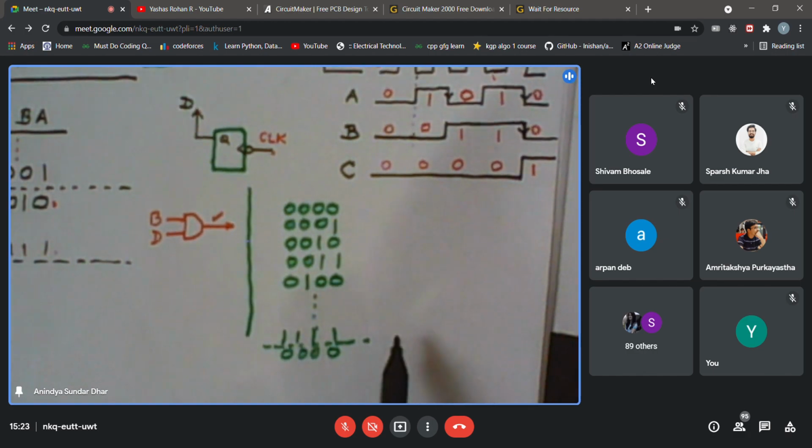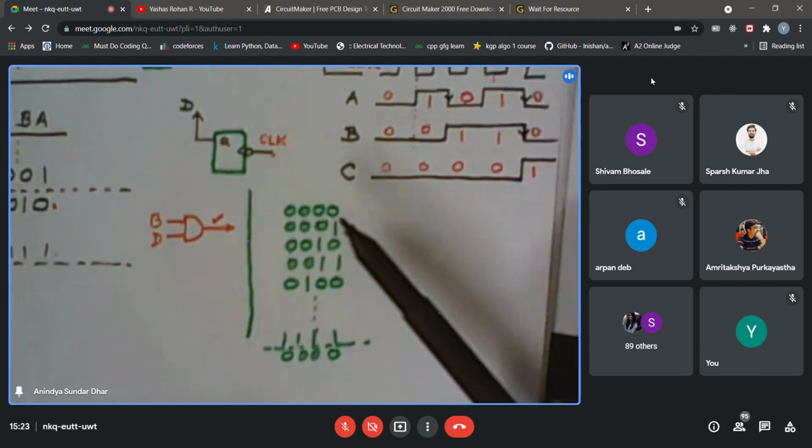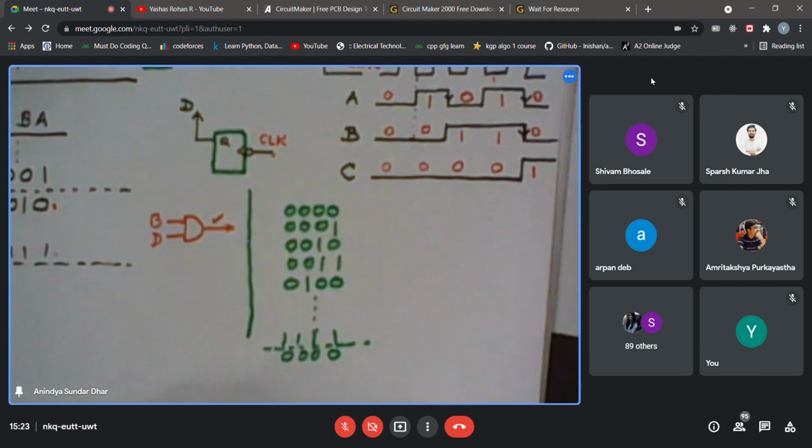I would like to design some block that checks whether all the bits are 0 and makes the output high only for this period, as long as they are 0. Once it becomes 0001, that will fall. Can you suggest a circuit that will test whether all four counter outputs are 0?